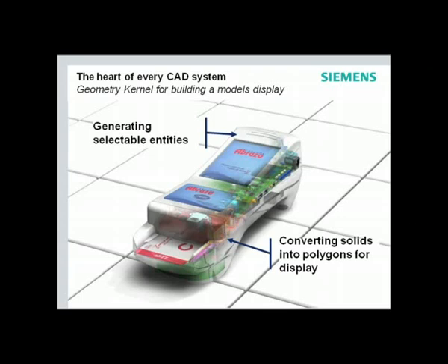You personally, as the CAD user, never see that, but it breaks it down into a triangle mesh, and then using some shading averaging techniques, it sends that triangle mesh to the video card, which actually does the shading averaging. That makes it then appear like a continuous solid. And typically that technology, called tessellation, is also provided by the kernel.